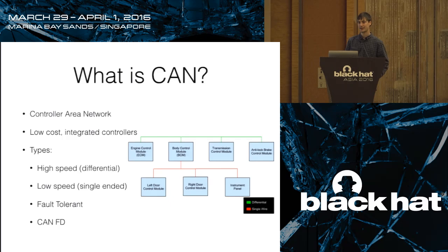And in a lot of systems now you see gateways. This is sort of a naive, really simple, fits on a slide diagram. Real automotive architectures are quite a bit more detailed and complex and are also typically proprietary, so I can't put them on a slide. But this has a BCM, or a body control module, acting as a gateway between two buses. So it will let you get messages or get data from one bus onto another.